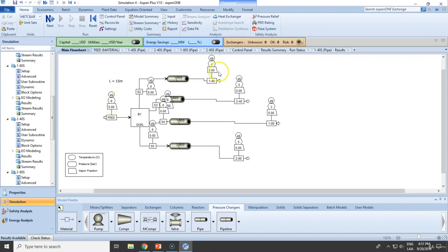So it drops from 6 to 4, 6 to 5, 6 to 3, and 6 to 5. Apparently this is the greatest pressure drop, essentially because the same size but higher schedule implies that the inner diameter is decreasing. Therefore, the velocity increases, which requires a pressure drop. Okay, so that seems nice.